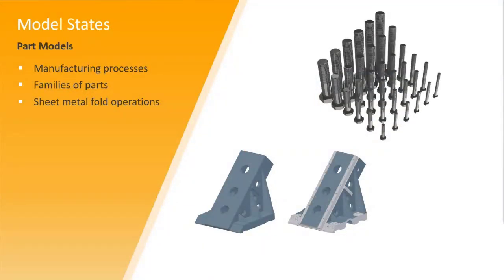Model state part. Model state is a powerful new workflow that enables you to create multiple representations of a part or assembly within a single document, to provide a convenient way to engineer, manage, and manufacture your design with different dimensions and parameters, component properties, or simplification. Because the variation exists in one file, there is no need to worry about breaking association between files.